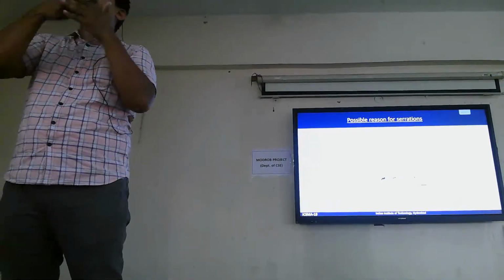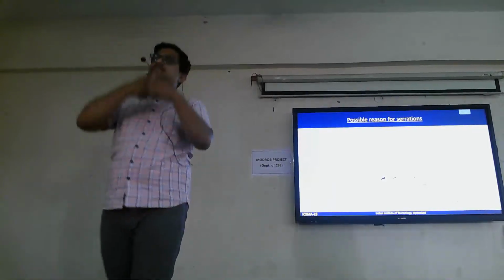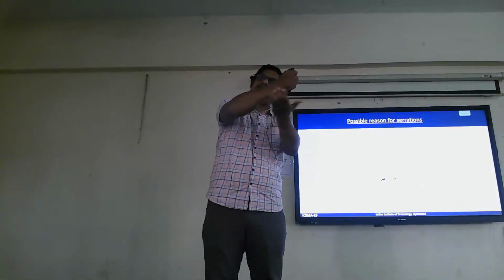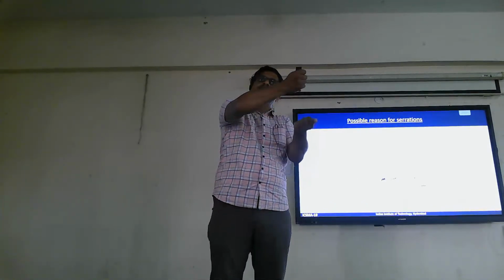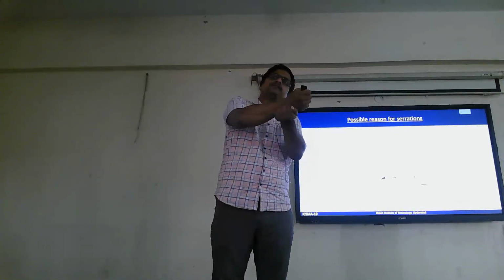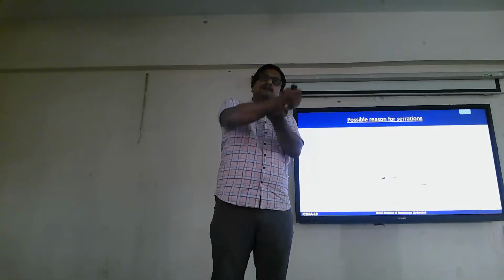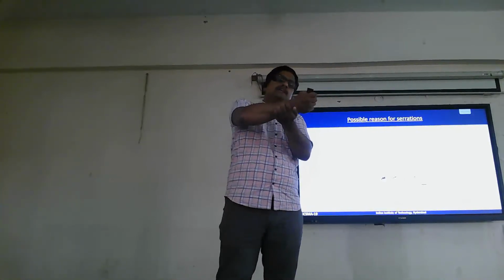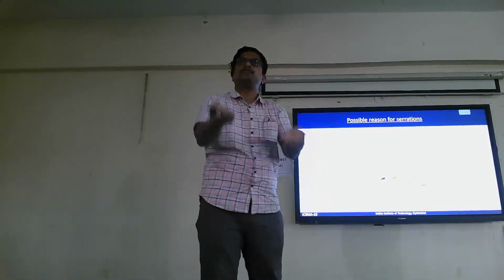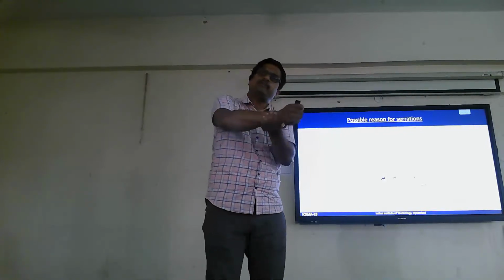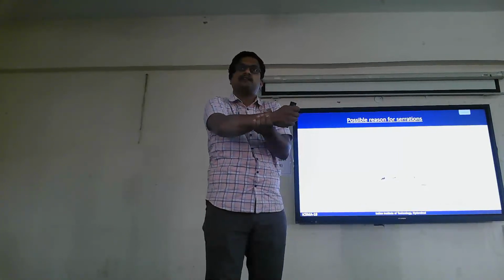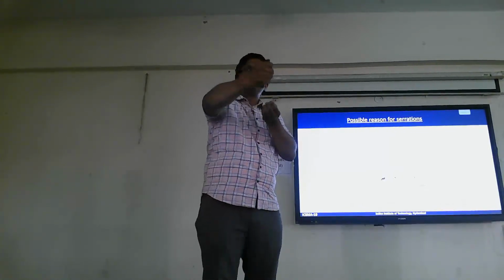So basically, this is how solute-dislocation interaction happens. At a particular velocity of the dislocations, the solute atoms go and form an atmosphere below the dislocation line. Because the solute atoms sit there, the energy of the dislocation decreases, so the solute atoms want to sit below the dislocation line. The moment they sit there, the dislocation doesn't want to go further, because moving out of the solute atmosphere increases the strength required. So the solute atoms are holding the dislocation line. But if you increase the stress, suddenly the dislocation will break out of it.